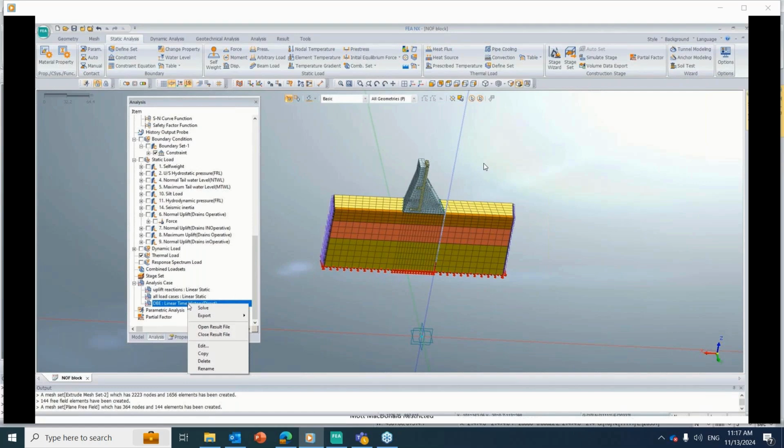But now we have this finite element method with us. We can actually simulate the actual geometry of our structure. We can actually simulate the ground with the actual geotechnical properties, and we can actually simulate the shaking of the ground. We don't have to apply the force on the structure itself. Let the structure behave as per the shaking of the ground. Okay, so those criteria are not applicable here.